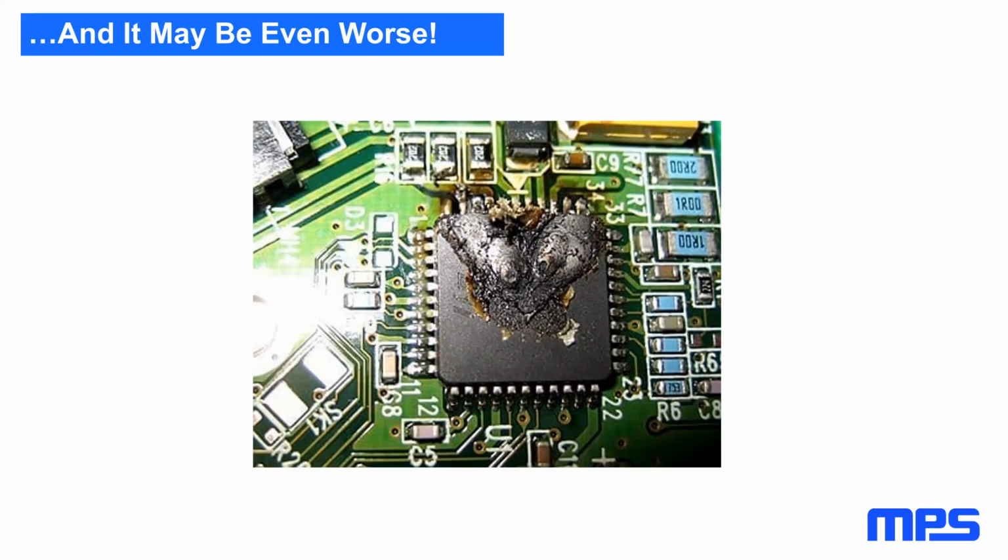The other thing you can do, which I usually suggest, is to build it and test it. I've been surprised quite a few times by a circuit being able to deliver more current than the calculations showed. It's especially true if your PCB design has really good thermal performance with lots of heavy copper.